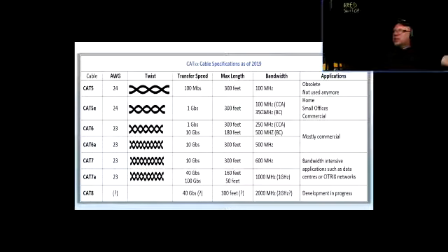It is capable of transmitting 100 megahertz of analog signal when we have copper-cladded aluminum, or it is able to have 350 megahertz if it's bare copper, BC. So that's where this thing already is playing a role here, right?